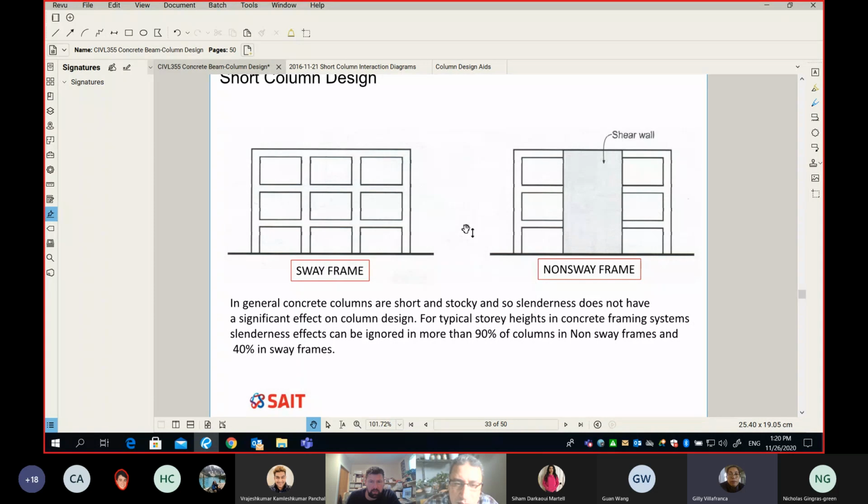You have to put bracing, yeah. I said, guys, listen, bracing and shear walls are equivalent. Both of them fall under the right picture, non-sway frame. Okay? Maybe it's difficult for you, so I'm going to tell you what happens if we're not allowed to place a bracing or a shear wall.